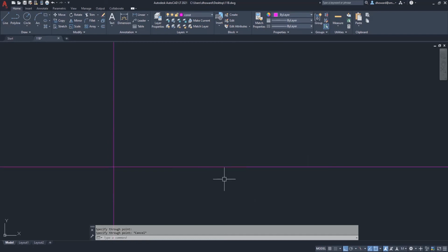They are. That's going to be my starting point. And looking at this object, I can see that the top view is really the most important view. And then second, I would say, would be the right side view. And the front view is the last view that is of interest to me. It conveys the least amount of information. So the top view is really where it's at, and that's what I'm going to start with.